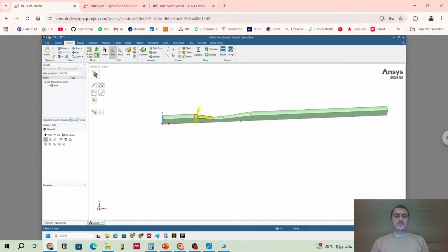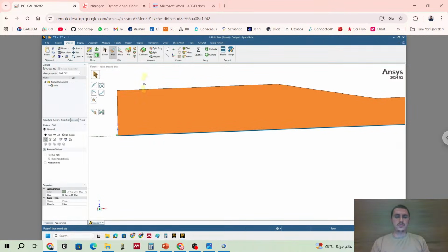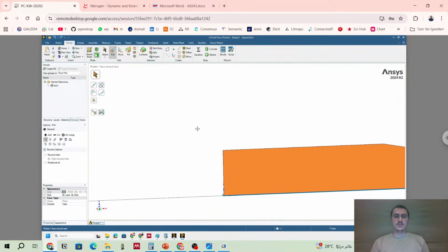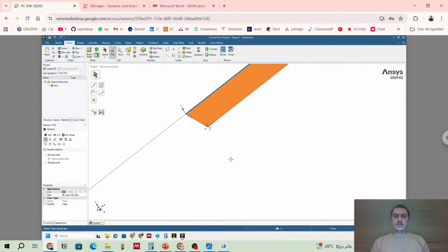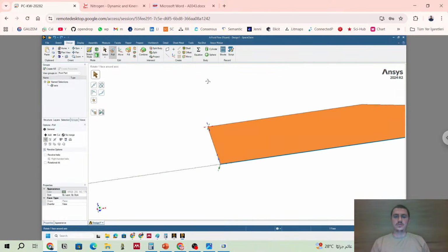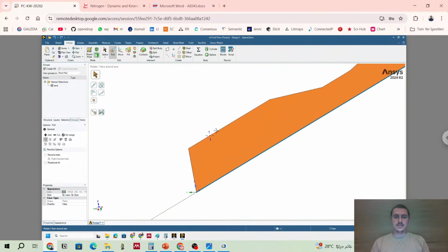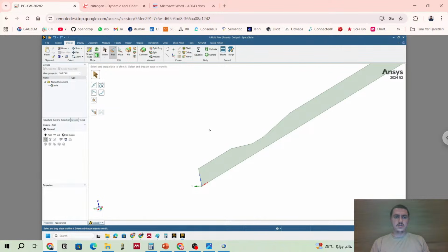Okay, let me focus to show you. Let's come back. Let's just zoom by scroll. If you press Control and the cursor, you can move it translationally. If you just click on the cursor, then rotate, spin it, so you can also roll your geometry. Okay, so we want to just look at this side, what we are doing, how we revolve this geometry. You see? Okay, pull, click, revolve, then select axis. It needs an axis from you. You see? When you select the axis, it shows you.